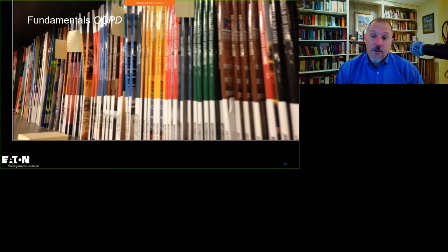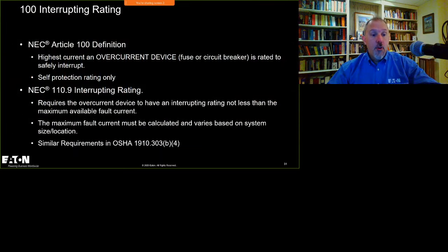That would be my answer. I don't know if that's right or wrong or different. That would be my educated guess based upon what I know about the NEC. The NEC says you can use the next size up, and so that means you can adjust it up to that next size. My suggestion would be to match the conductor ampacity, but I don't see anything in the code that addresses that scenario that you just raised about adjusting it exactly to it or adjusting it to the next size higher. All right. Okay, so let's boogie back to our regularly scheduled program.